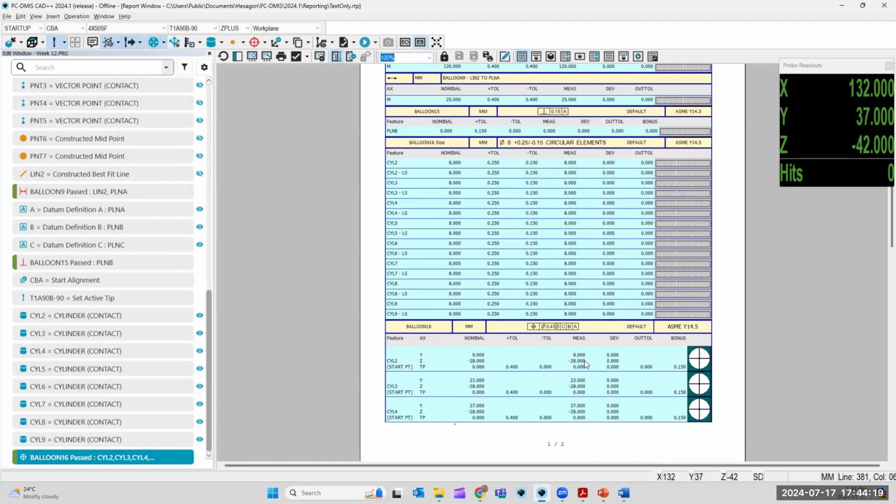And then there's a measured value, what the actual position of that would be. But that position isn't necessarily a plus or minus like it would be in a standard dimension. It's true position. So there's a cylindrical tolerance zone. It's not a square tolerance zone. It's circular or cylindrical. So you get a bit of a bonus tolerance if the size is different. It'll account for the bonus and it'll report the position graphically here.